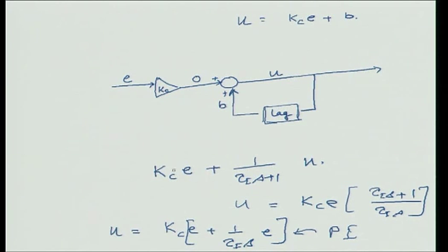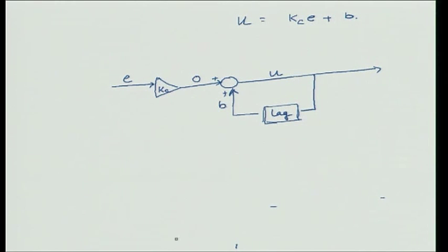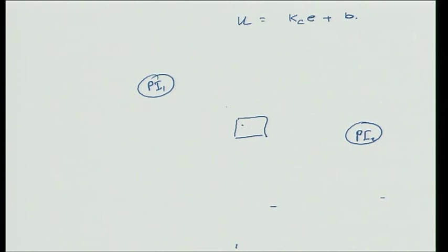Okay. Now, in terms of overrides, the thing that I was talking about, when I am doing my overrides, let us say I get back to the same thing as before, where two PI controllers are competing for control of a valve. So, I have PI controller number 1 and PI controller number 2, and both of these are competing through a low select or a high select.